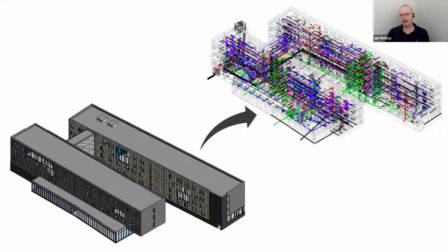It wasn't just so that we could provide a way to do this type of analysis in Revit. That's a cool thing to do. The other reason this makes it extremely interesting is the fact that the only reason any of the ductwork, pipework exists or is where it is is because there's equipment in that building that's serving a function that was basically decided by an engineer doing the systems analysis, right? So whether we had one water source heat pump serving 4 spaces or 1 space, or 2 air handlers, two heat recovery units versus 1, they're key decisions that are all part of that analysis earlier on. That information is now in the Revit model and can be used as the basis to manage that downstream.